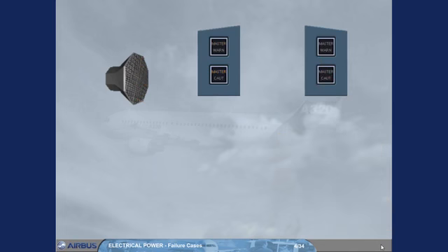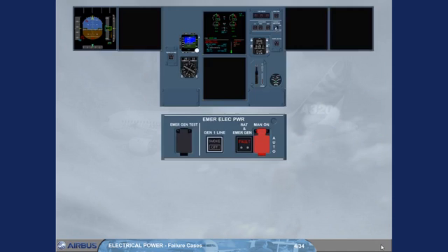After clearing the master lights and stopping the alarms, observe that on the emergency electrical power panel, the red RAT and emergency generator fault light is illuminated, meaning that the emergency generator is not yet online. After a short lapse of time, the RAT and the emergency generator light disappears. The emergency generator is now running and supplying the system. Notice that with the emergency generator online, the power supply to the captain's ND has been restored. Note, MCDU1 is also recovered.